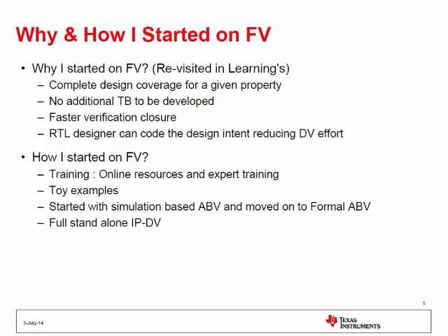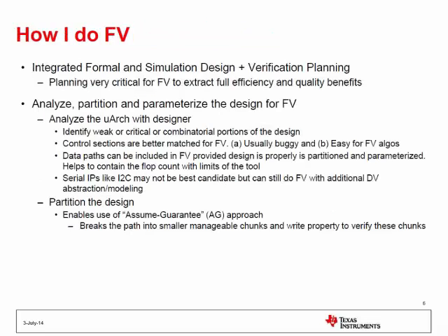first and foremost, I'd like to very clearly mention that the planning for formal verification is much more stringent and disciplined than what you usually do for a simulation verification. The word to stress here is integrated. Actually, it's an integrated formal, simulation and design. Why I'm saying formal, simulation, design, you'll see as we go through the slides, because formal is not going to be a complete solution for you. So you need to have some things you need to do in simulation too, and there is a lot of help you'll need from the designers to make sure you are able to achieve your goals.